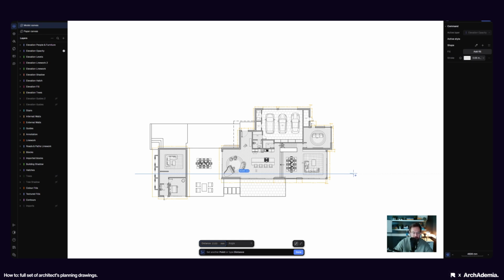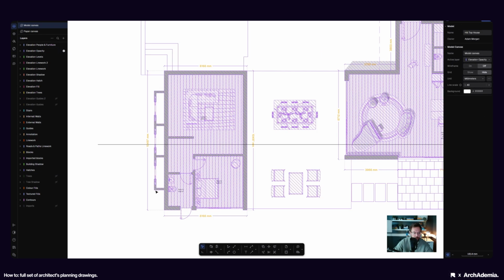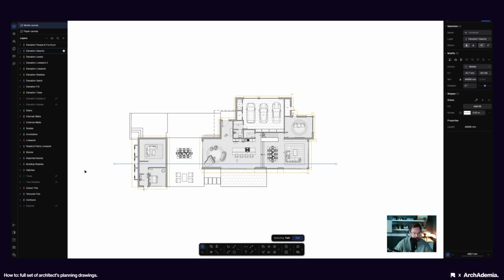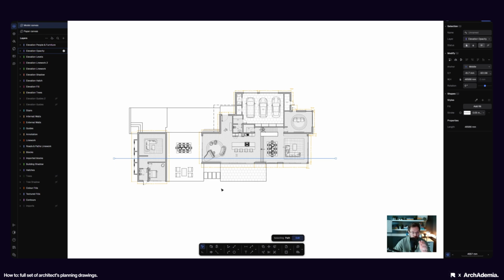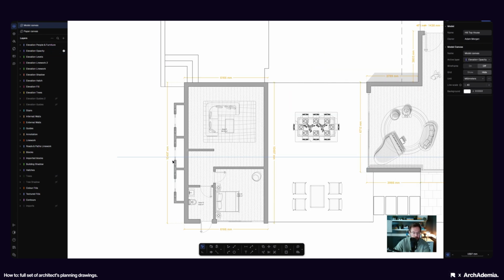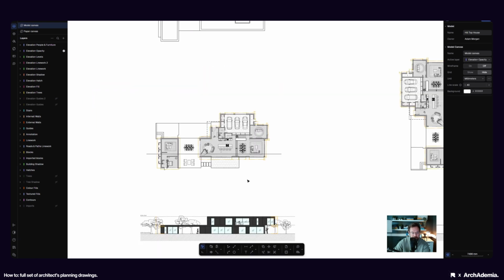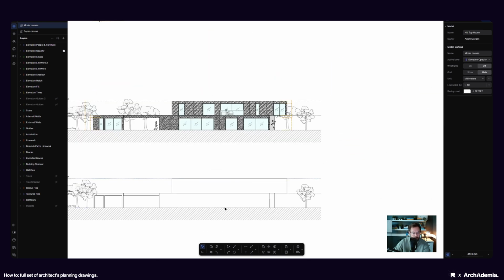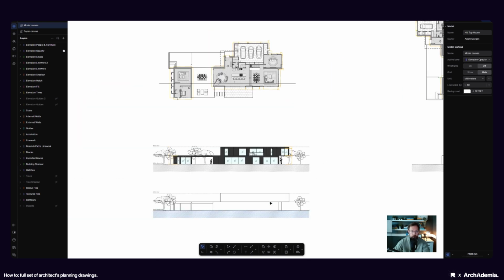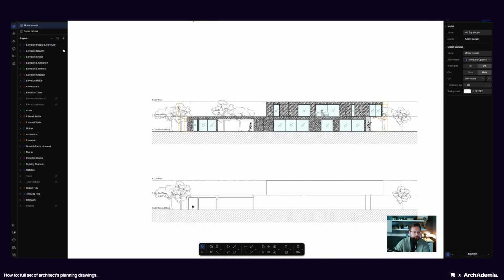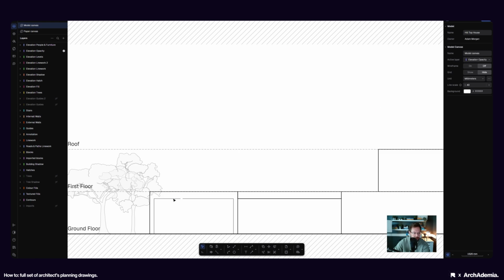So you need to decide on a cut. Now, the line that you cut through, that's the thing that gives you the information to strike your lines down from. So we've actually only got a couple of external walls there, glazing there, and actually that steps down. So we could show a little step in our ground plane. So we actually don't need that one.